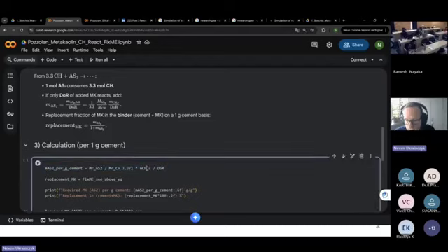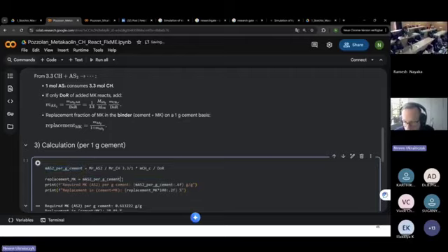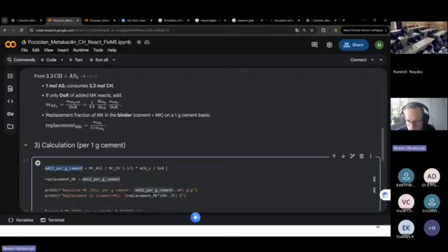And then multiplied by the mass of portlandite and divided by the degree of reaction of metakaolinite. So this will give us the mass of metakaolinite per gram of cement. And now we just need to do the ratio, the replacement level, which again, just copy this variable here, which is the solution of this stoichiometry. And we said we have 1 plus, so this will be the replacement level.